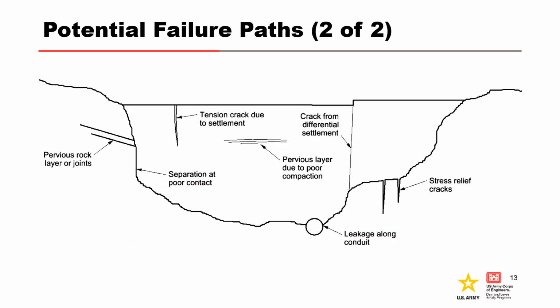This figure shows some common locations where cracks and defects are often observed. The worst location is usually where two or more factors combine. Understanding the design of the dam, given the geology and seepage history, are key. Searching for potential flaw locations is a very important step in the risk assessment.